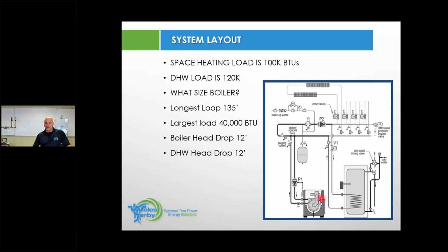The boiler will have a 20-degree delta T. So you can use your universal hydronic formula to figure out your flow rate. And that will help you figure out your circulators. You will use page 55 in your TACO book to find your circulator curve chart. It will be the top chart on page 55 that you're looking for in this exercise.